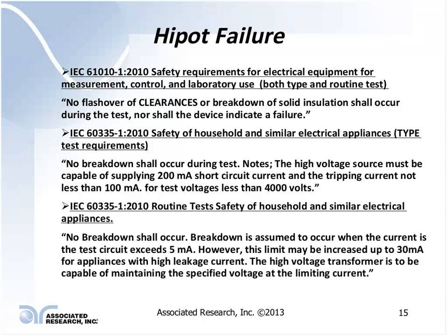They're not degreed electrical engineers or technicians, so they may not know all the hazards and how to avoid them, even though the OSHA standards dictate that they should. But 100 milliamps of current can be lethal. If the operator makes a mistake with that, it may be the last one they will ever make. Keep that in mind.